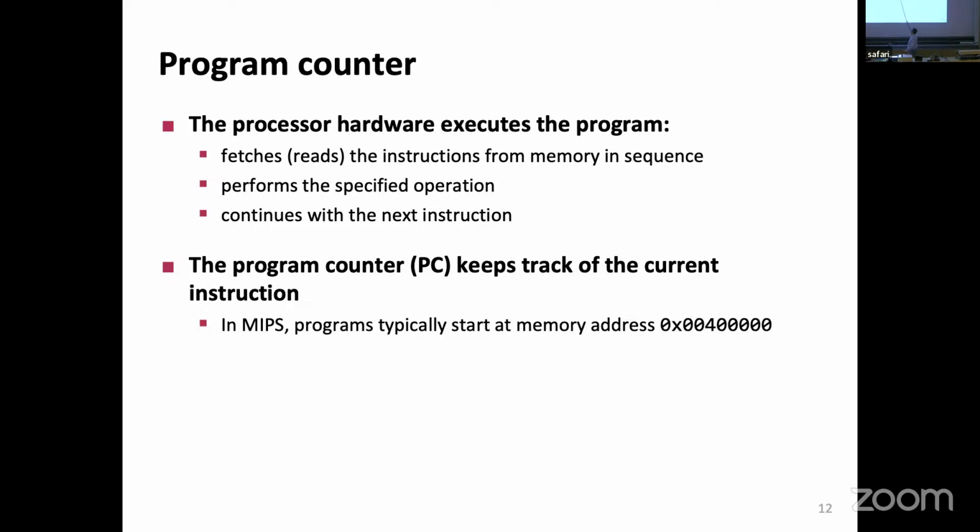And we say we have a special counter that's not part of the registers, and that counter shows me in memory where I should start fetching the instructions. Normally, he will go one by one. So he goes to the address. How do I know where I start? Well, it's already agreed upon, a gentleman's agreement if you want. Whenever you press the reset button, the program counter goes to this weird address. So whatever you do, the first thing that boots in the memory, in the processor, should be located at this address. Reset, release it, look at the 32-bit value, bring it to the processor.